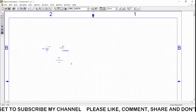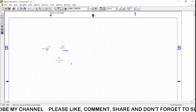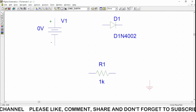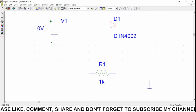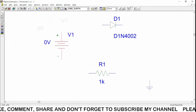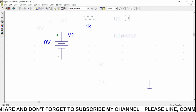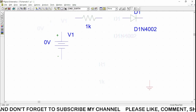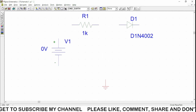I'm going to press escape, so it will be gone. I'm going to set this to zoom to fit page, so it will fit to the page. So you look at here, this is zoom to fit page. Then I'm going to take this VDC and place it over here. Then we need a resistor over here, a diode over here, and then the ground terminal over here. I'm going to fit the page again.